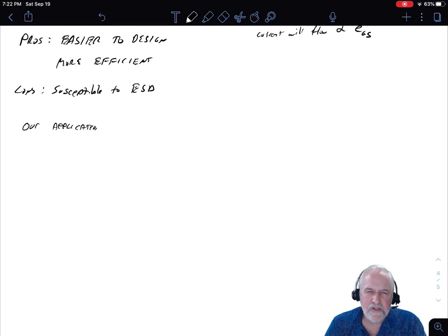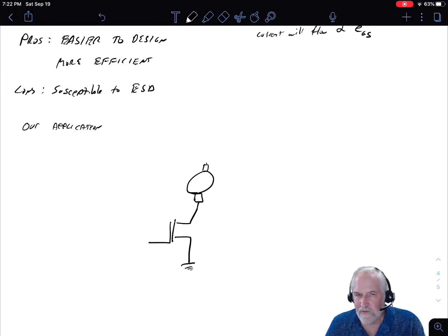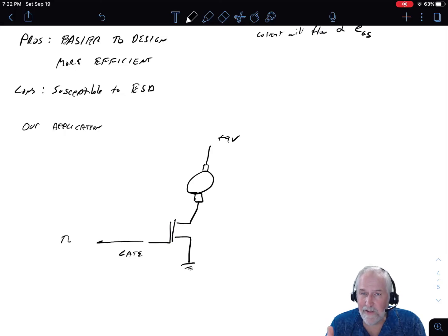The cons are they're susceptible to electrostatic discharge. Like a lot of computer components, because they have these things in them. If you're in a carpeted room in the wintertime when it's dry, you walk across the room, touch the doorknob, you get zap, right? You get that shock. By the way, that shock is like 10 to 20,000 volts, hardly any current, but it's that voltage that tends to break down the barriers inside these integrated circuits. They're making them a little more robust than they were 10, 20 years ago, so it's less of an issue now, but it's something to be aware of.